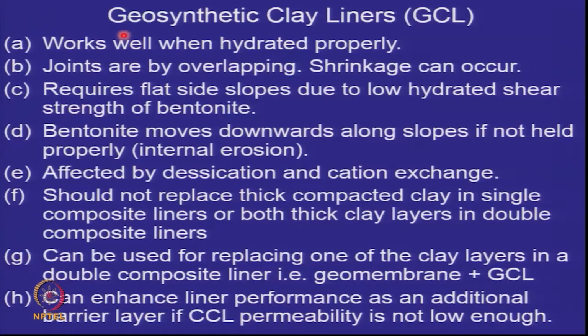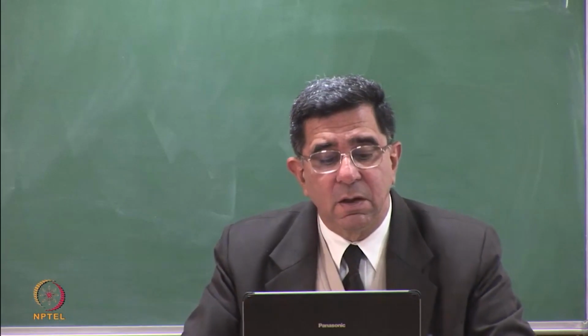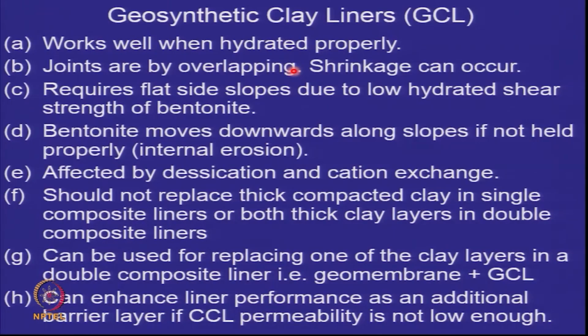So geosynthetic clay liners, the experience shows, work well when hydrated properly. That means they must have been given adequate moisture to swell. Otherwise, air will pass through them and water will pass through them. Joints are by overlapping. They are no longer welded. Shrinkage can occur if they are allowed to dry out.